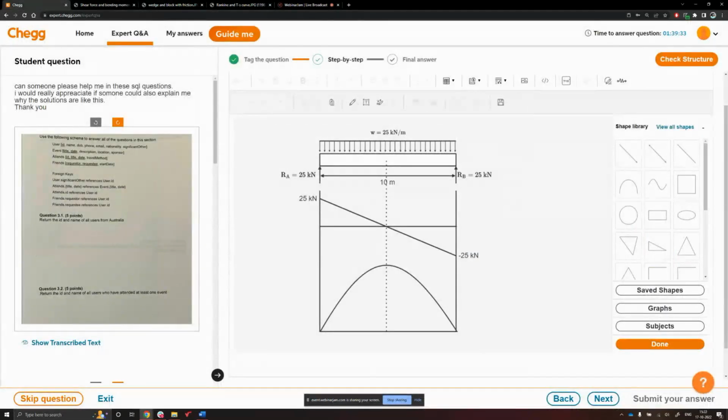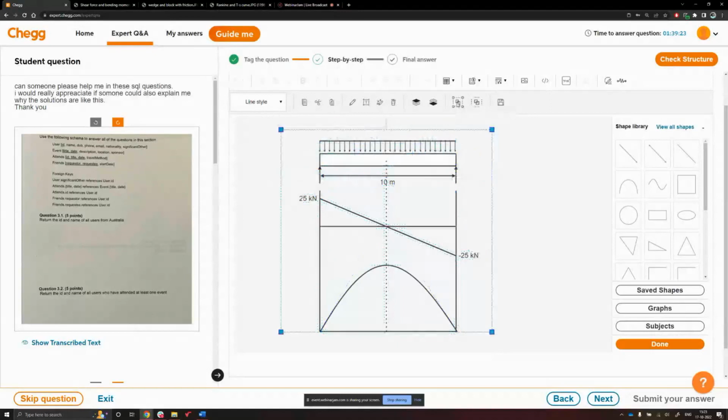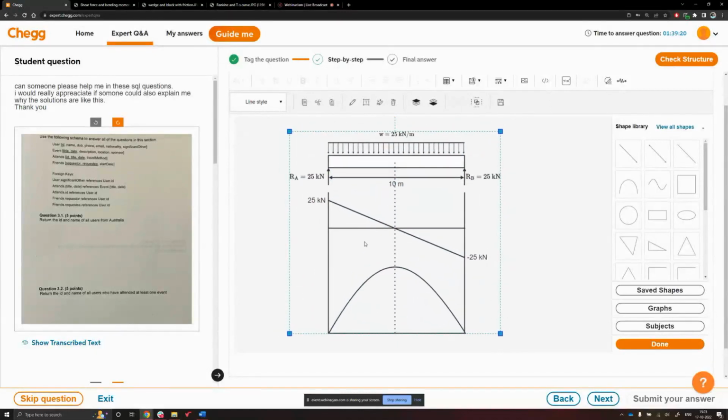One more feature I want to mention is there is an option to save the diagram. To save the diagram, you have to first select the whole diagram. It's better to group it so that it's easier to move. Otherwise, you can't move the diagram as a whole. After that, you can click on the floppy figure here, and give a name. Something like this. You click on save.